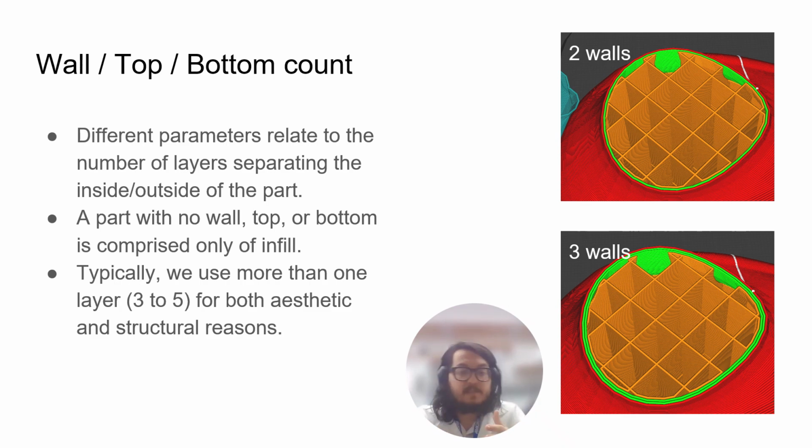You can have a faster printing speed where you end up making an uglier looking part, but if you do this on the inside walls, you don't really see them. Then you can do a very slow and more calm and higher quality skin or outer wall. If you're having parts that you're seeing holes through, or you're feeling that they're a little bit weaker, you can intensify their strength, and it will also take a little bit longer to print, but it will typically look nicer and also be stronger by increasing the wall counts.